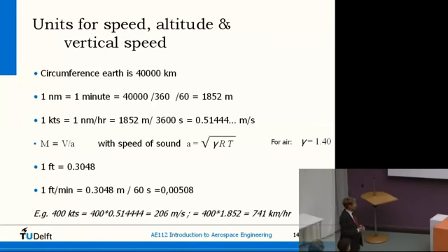So with most aircraft, you need to stay under the speed of sound. So it's mainly important to avoid going beyond a certain Mach number, also because of the load on the aircraft. So equivalent airspeed doesn't really work anymore. As soon as the shock waves play a role, you cannot express your maximum speed in equivalent airspeed, but you also need to cover the Mach number. So at some altitude, your maximum speed is determined by your Mach number and not your equivalent airspeed anymore.